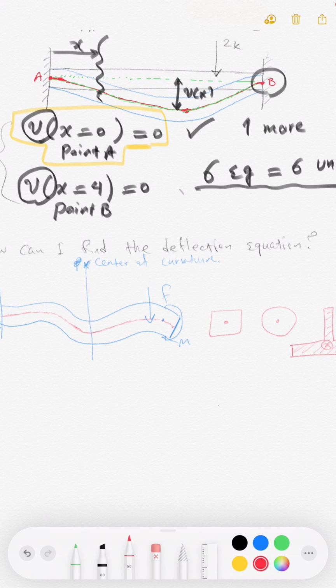Anyway, let's go back to this problem of cutting. So I'm considering, let's use green color, the center of the curvature. This is something else. It's not the centroid. The centroid is right here. You see the centroid of the cross section. They also call it the geometric center, so it has different names. But the center of curvature is the center that this curve for the neutral axis that I'm drawing in red right here is going to deflect toward.